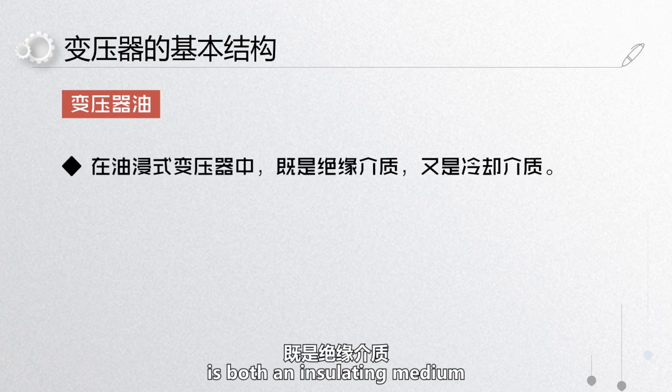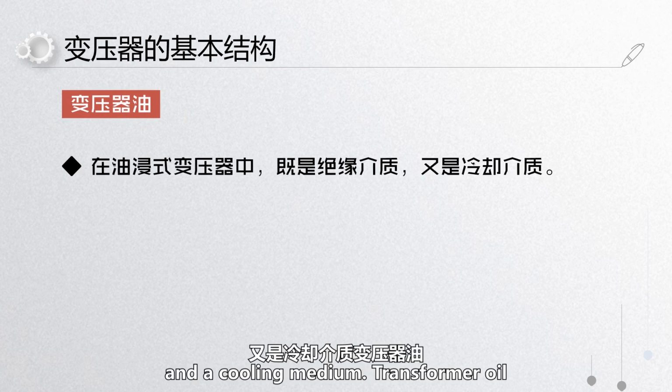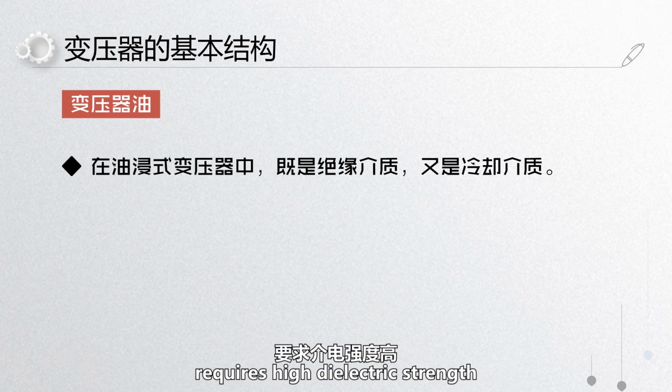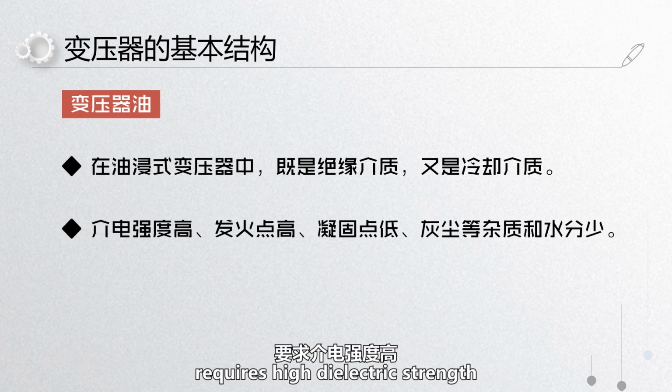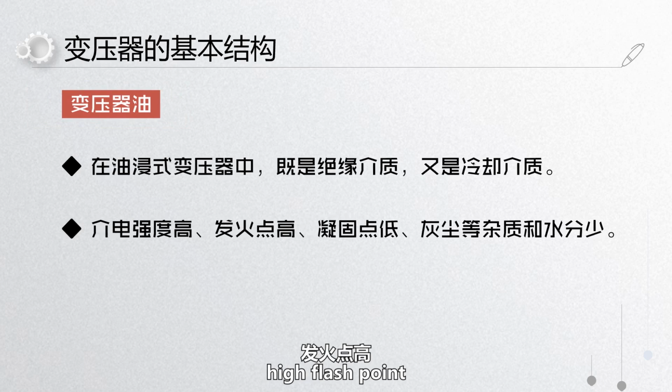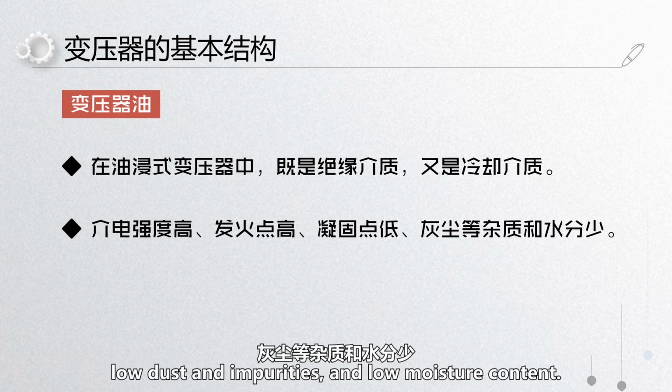Transformer oil is both an insulating medium and a cooling medium. Transformer oil requires high dielectric strength, high flash point, low pour point, low dust and impurities, and low moisture content.